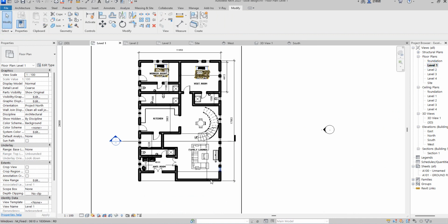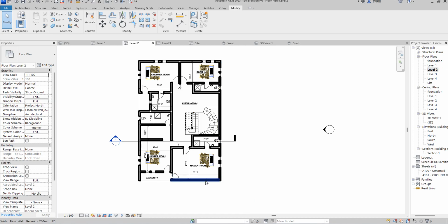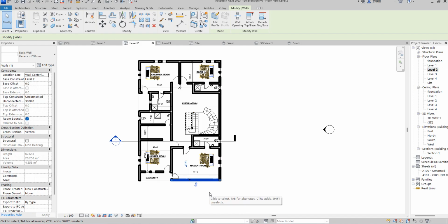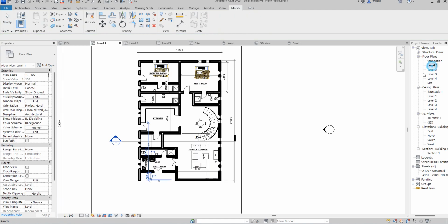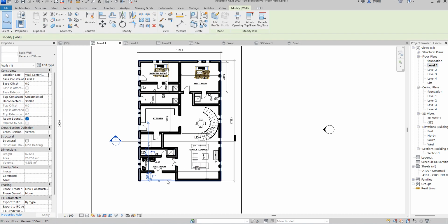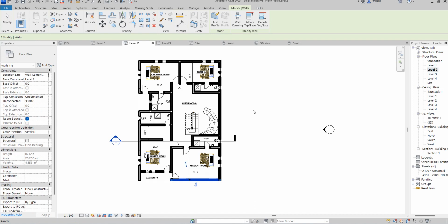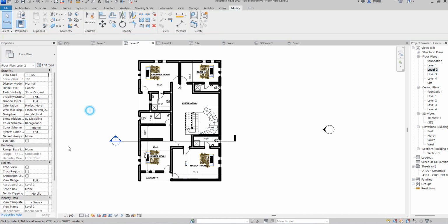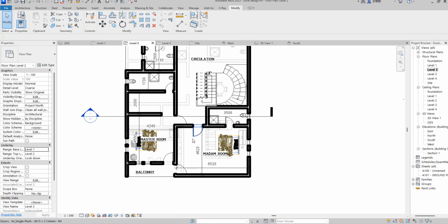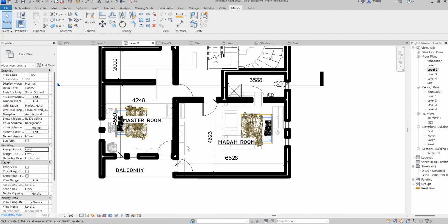So we go to the ground floor. Then we have a long window. So I'm going to delete this particular wall, because I just need a complete thing from down to the top. So how it happens, let me just click and see the underlay. So underlay for me, level 1. What is there is that there is an issue at this position. So what I need to do is to adjust the mass, because I want everything to fall in place.